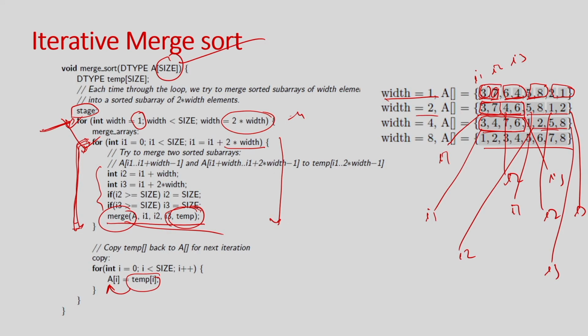Ideally you know that if I unroll, my area will blow up, because there is no loop, it will create this many copies, but it will run faster, my time to execute will reduce, right. So, earlier if the loop executed 10 times, and if I unroll, it might take 1 or 2 clocks to complete. Ideally 1, but because of some dependencies it might take 2-3 clocks. So, the design will be faster, but the area overhead will be more, and the pipeline is kind of a trade off, right. The area overhead is not that significant, because you just have to add some pipeline stages, and probably you cannot share some of the resources because the stages are happening independently.